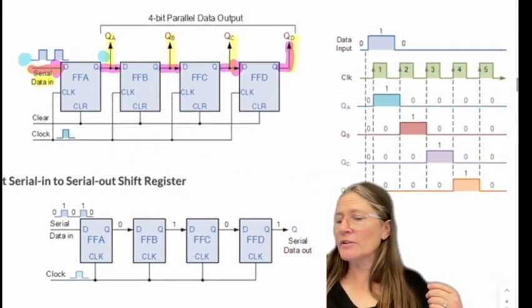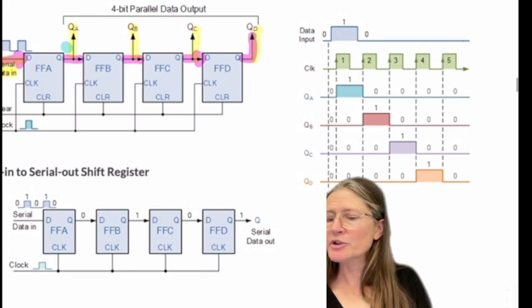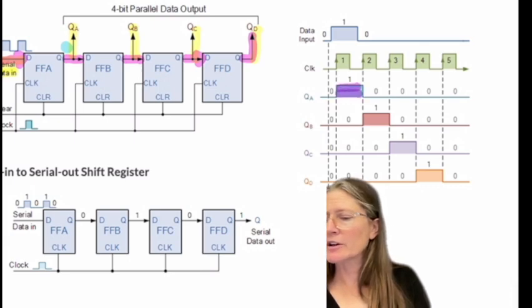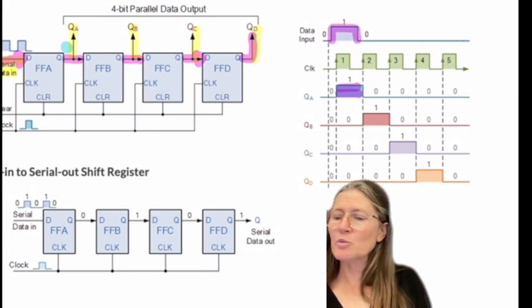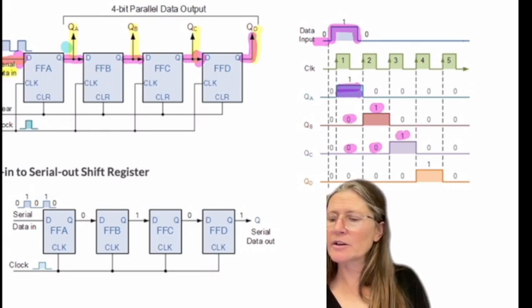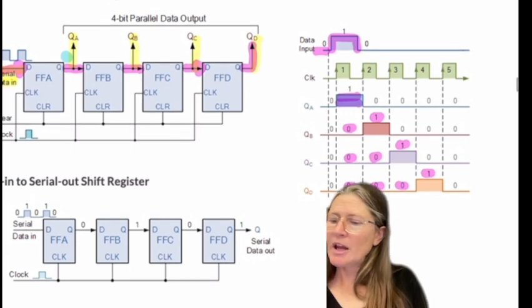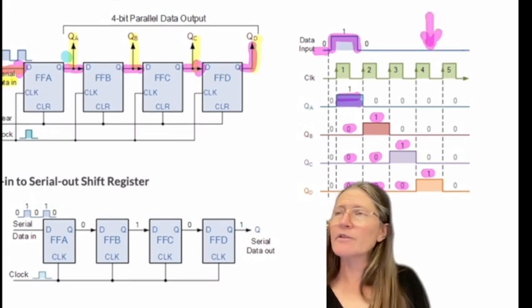Okay, so you can see here, first clock cycle, your 1 is here. Then if you have a 0, so at clock cycle 1, you have a 1 go in, and then everything else is going to be a 0 after that. So the 0 becomes here, 1 is there, then 0, 0, and then the 1, and then 0, 0, 0, 1. And then I'm going to read it at the 4th clock cycle.